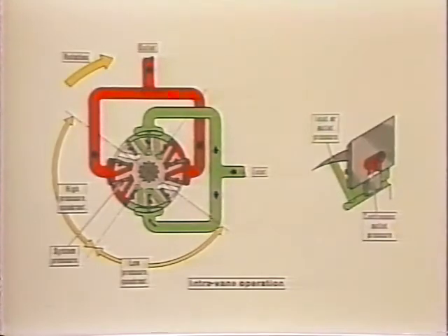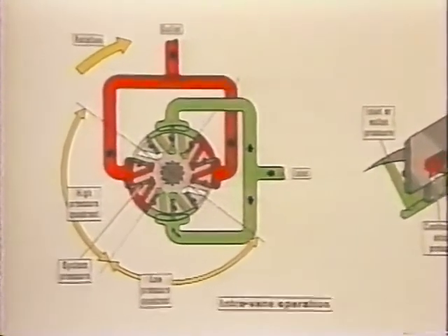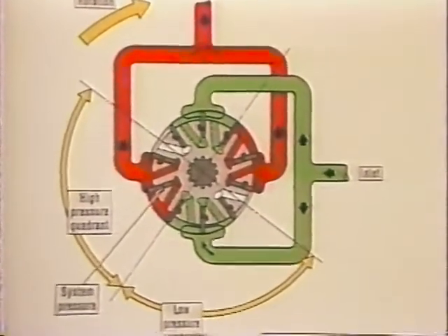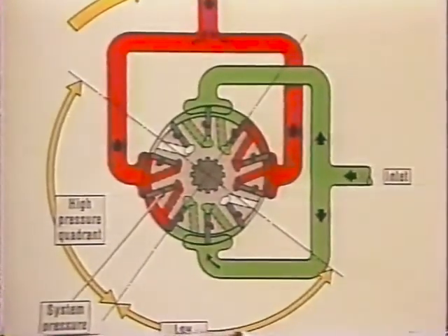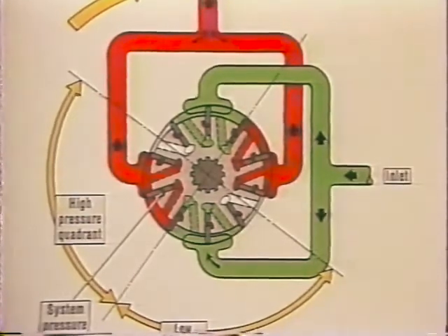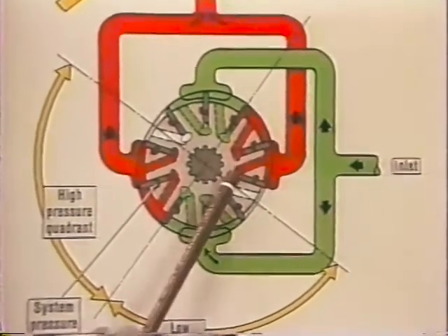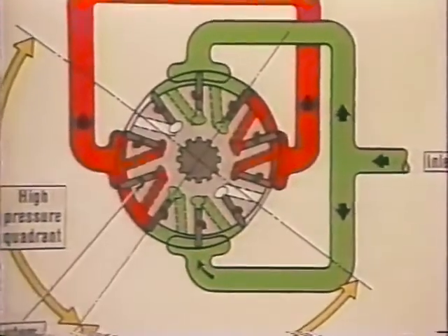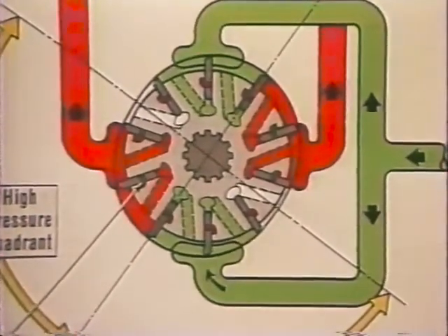In these pumps, with their large vanes and high pressures, the forces involved could reduce both ring and vane life due to high vane tip loading. Remember, force equals pressure times area. As a remedy, holes were drilled through each rotor segment, extending from its outer surface to the bottom of the vane slot ahead of it.